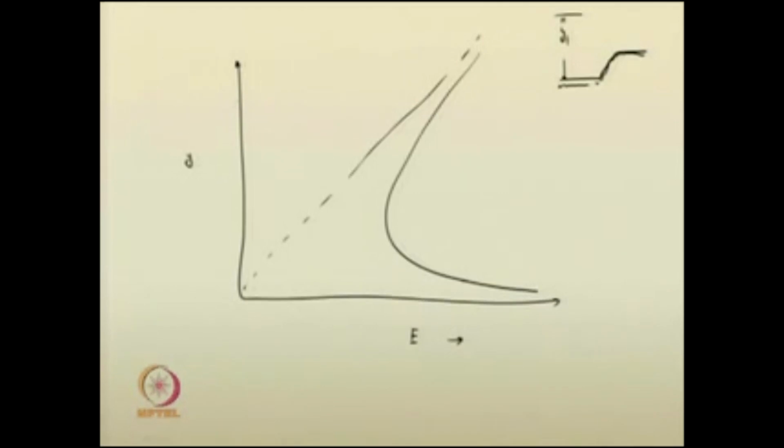For the y 1 value, you evaluate the specific energy E 1. With the hump elevation del z, you take E 1 minus del z, and you will get the corresponding value somewhere here.